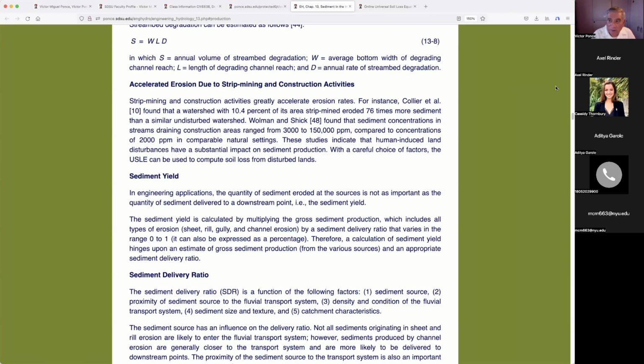Now, in this country, we have regulations about that. We have the so-called best management practices. I don't know who invented that term. It's kind of a misleading term. I don't like it, but still I have to live with it. BMPs, you heard about BMPs, they're very common. BMPs are the management practices to control erosion in the construction site. So the idea is to do whatever is necessary mechanically and otherwise to make sure that the sediment does not leave the premises, that it stays there.